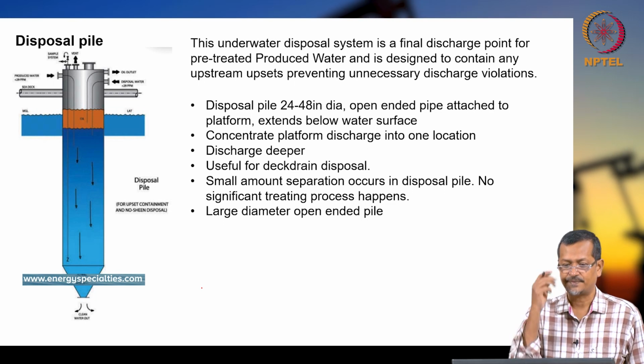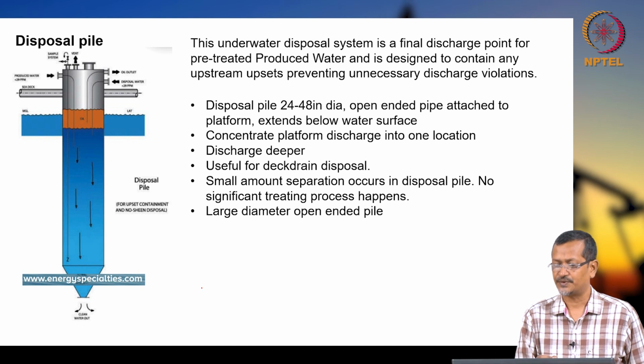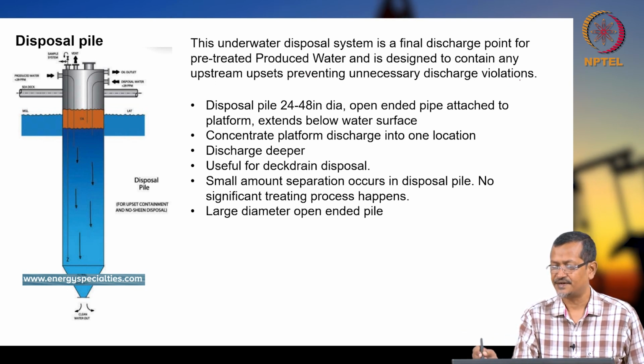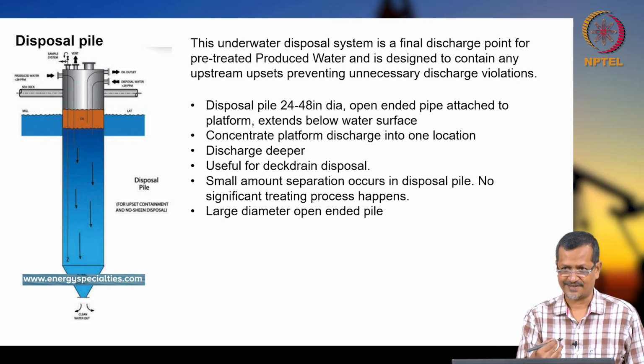And you see one disposal pile. This underwater disposal system is the final discharge point for pre-treated produced water and is designed to contain any upstream upsets, preventing unnecessary discharge violations. So, this is the last stage of water disposal for offshore application.